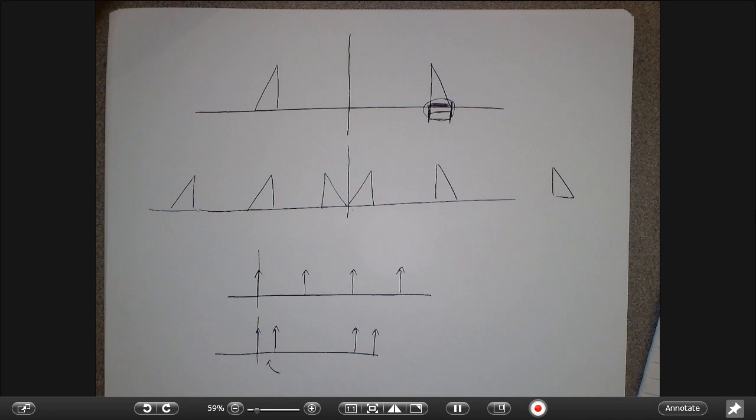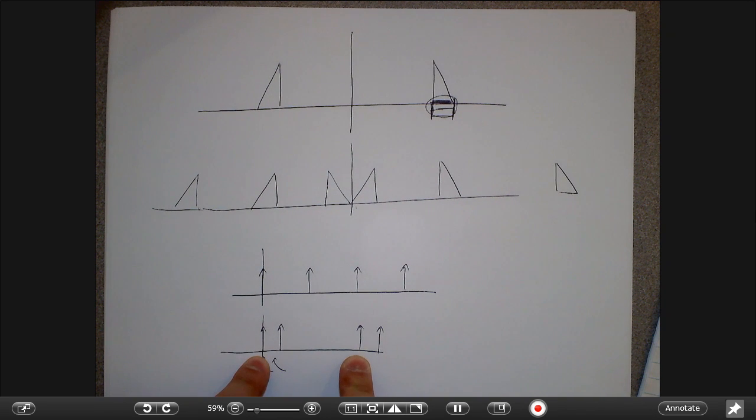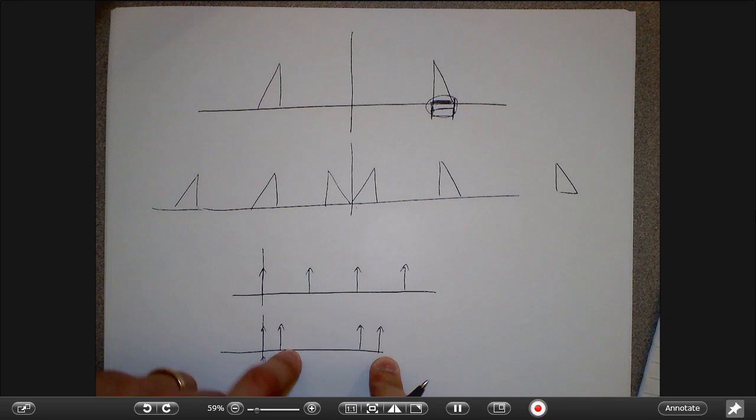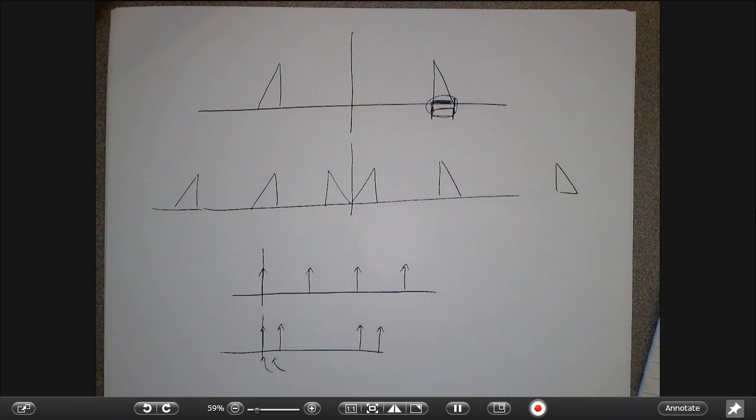You can see from the solutions that you've got a similar idea: this set of impulse trains gives me one set of copies, this gives me another set of copies. And you think about how I have to make sure these copies cancel each other out the right way in the frequency domain. In fact, there are all sorts of variations where I don't even necessarily have to do regular sampling in the frequency domain. Instead, I can do sampling almost randomly, as long as the expected value of the number of samples per period is the right number. So there are lots of interesting extensions to the sampling theorem.